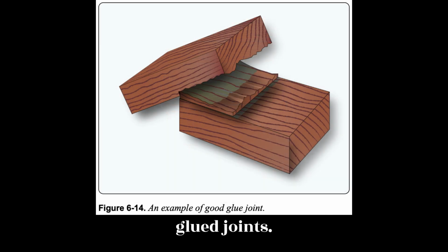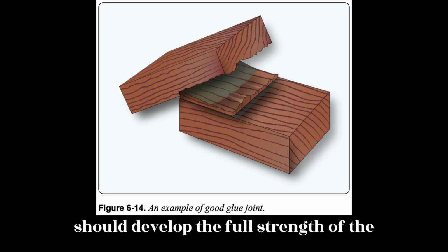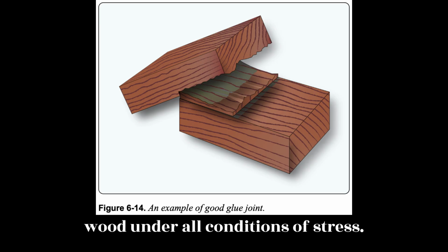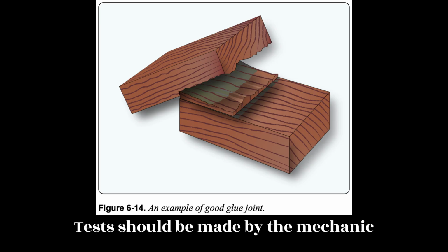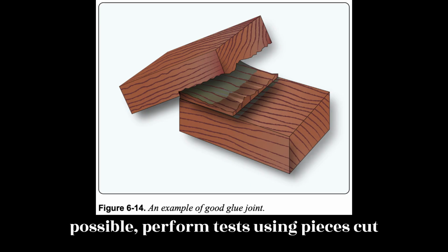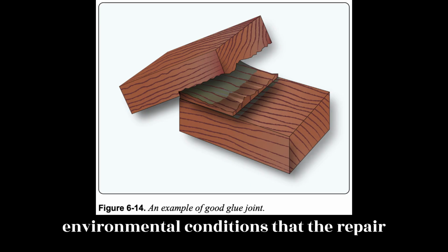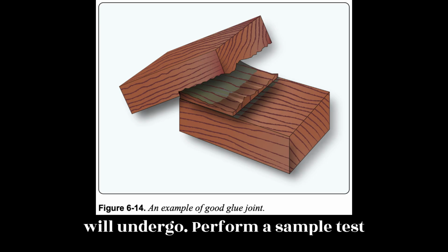Testing glued joints. Satisfactory glue joints in aircraft should develop the full strength of the wood under all conditions of stress. Tests should be made by the mechanic prior to gluing a joint of a major repair, such as a wing spar. Whenever possible, perform tests using pieces cut from the actual wood used for the repair under the same mechanical and environmental conditions that the repair will undergo.